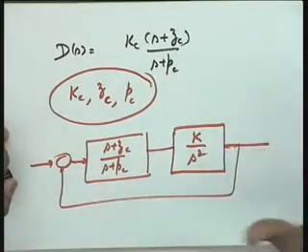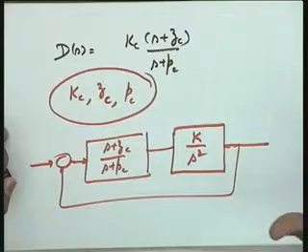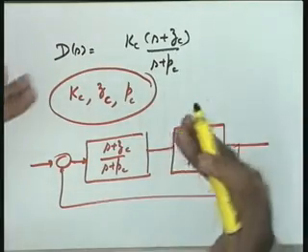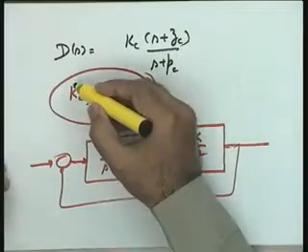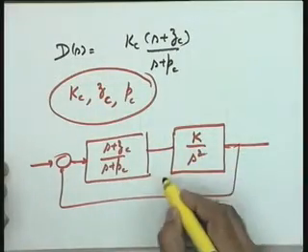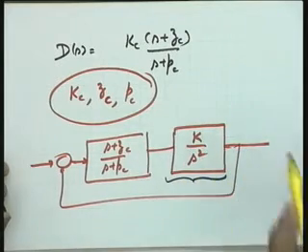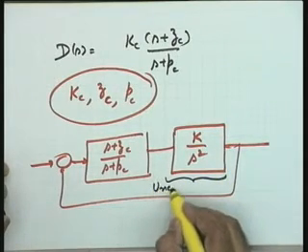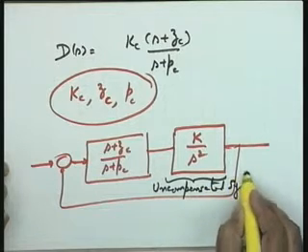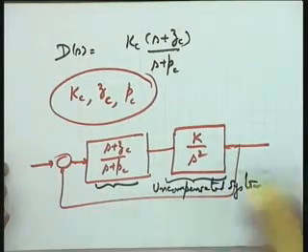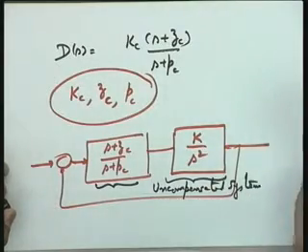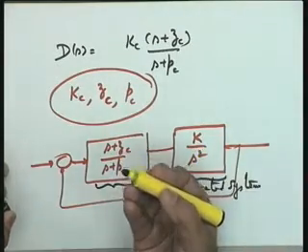So what I want to say is that the implementation of the total scheme depends upon the hardware, and I take the design procedure in such a way that there are three parameters K, Zc and Pc, and I will call this system an uncompensated system in my design terminology. Though you can see now, actually an uncompensated system is a partially compensated system, because one of the decisions you have already taken is about the gain, and that gain K is also a parameter of the compensator.